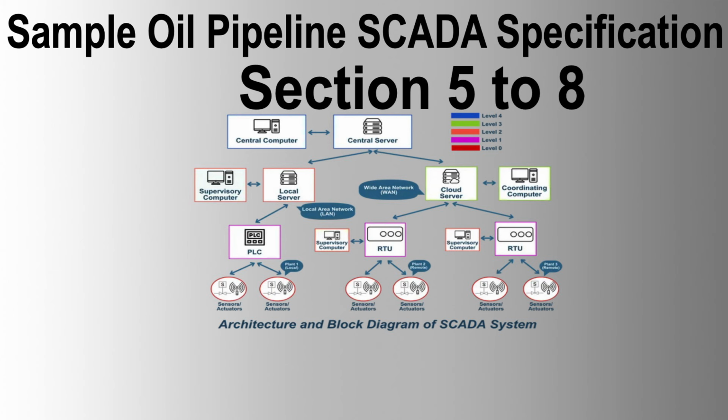5.14 Insulation and isolation requirements. Insulation designed to withstand 1.5 kV RMS, conforming to IEC 255-5 test standards. Isolation resistance more than 5 megohms. High-frequency disturbance designed to pass a 5 kV impulse test voltage, conforming to IEC 255 standards.